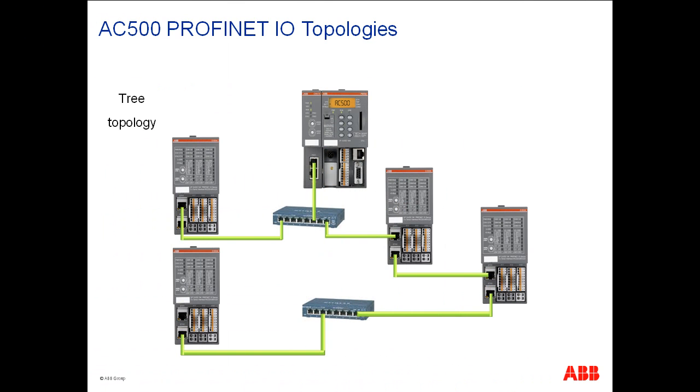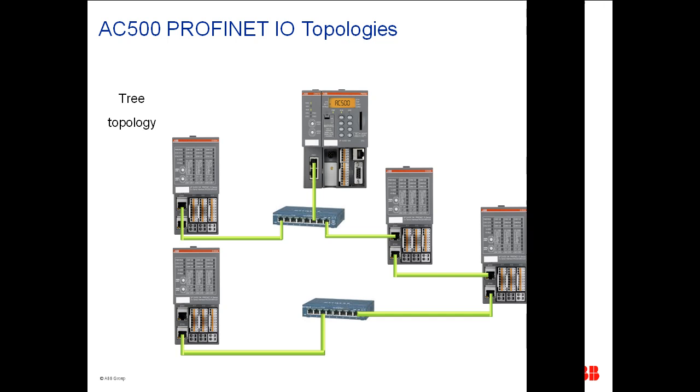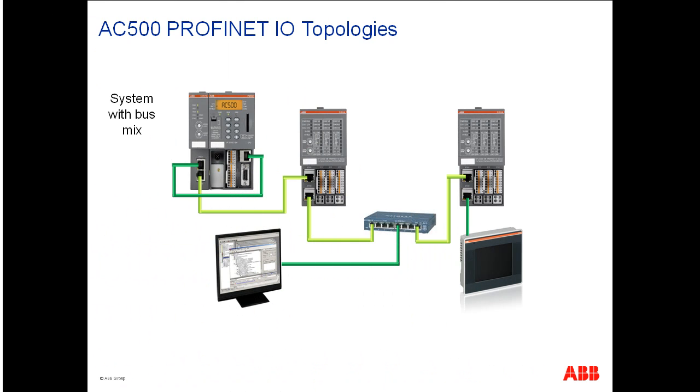What we see now is called the tree topology. Well, a tree topology is basically a combination of several star networks, typically meant for a large automation plant grouped into different manufacturing islands. In this example, the interesting point is the routing function. That is, an engineering station connected to a switch in TCP/IP protocol could in turn download a program to the AC500 controller over the Profinet network with appropriate settings.